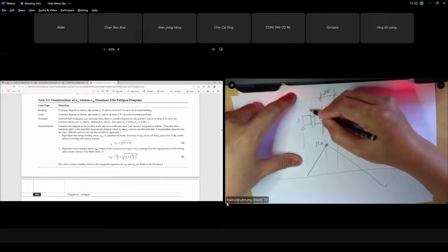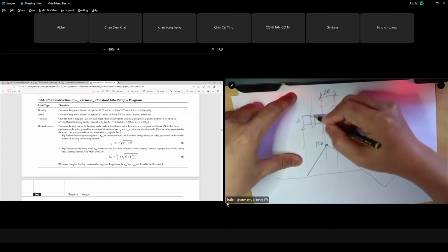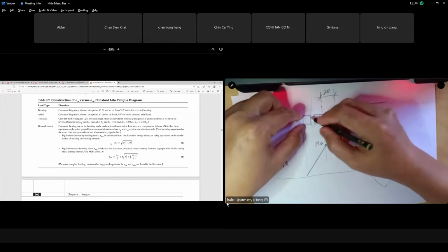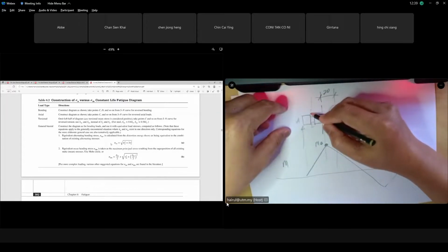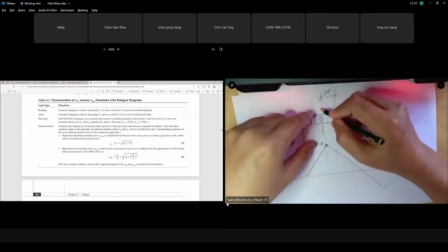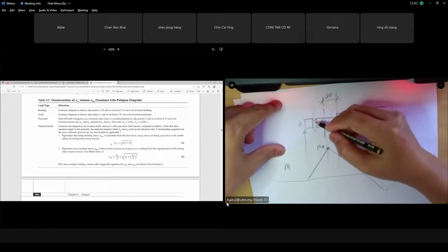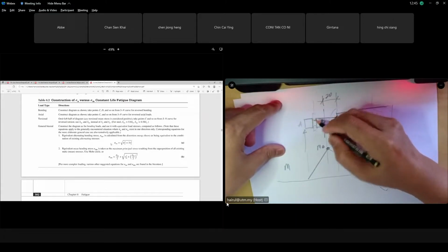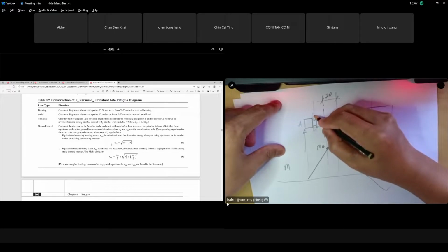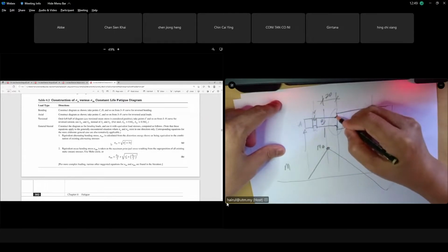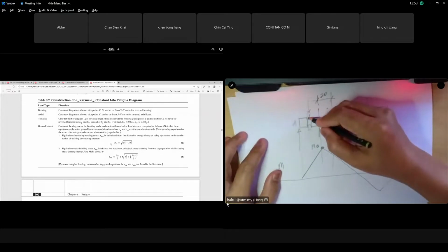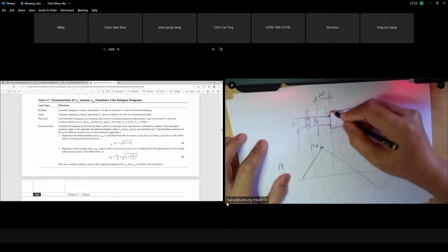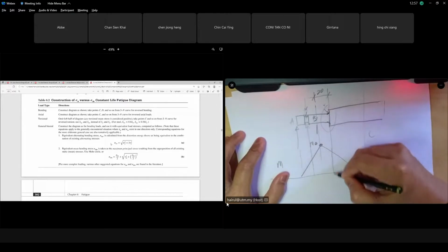So this is why there is a groove, where we have a snap fit ring to lock the pulley. The shaft has a groove here with a small radius. Also here, the fillet at the shoulder has a small radius. This is our point of interest that we need to consider, based on our moment diagram.